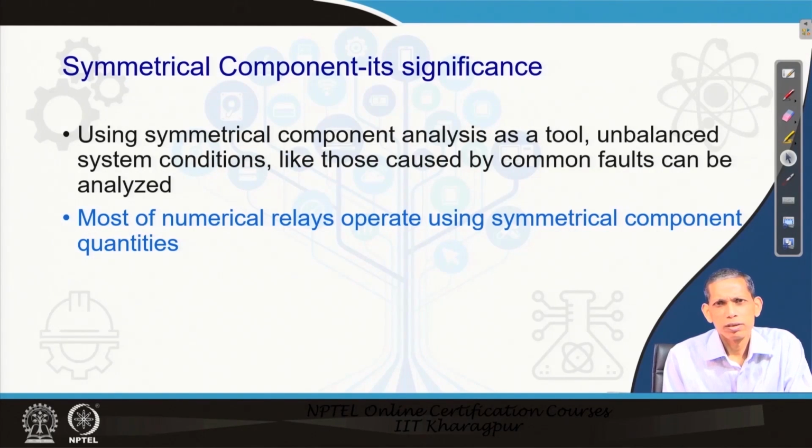Further, it is found that most of the numerical relays today use symmetrical components for the decision making process, and as I mentioned, such fault analysis is also very useful while considering the circuit breaker rating or different relay settings in the system.